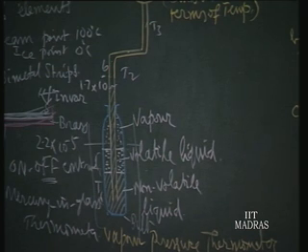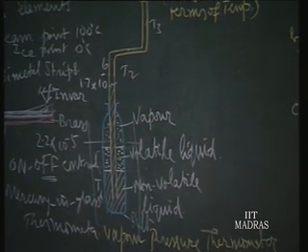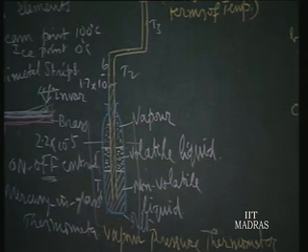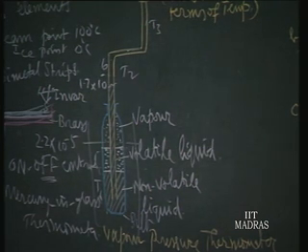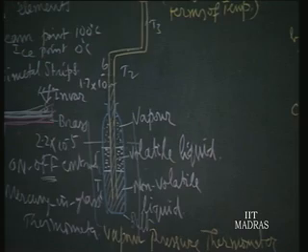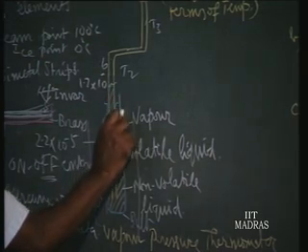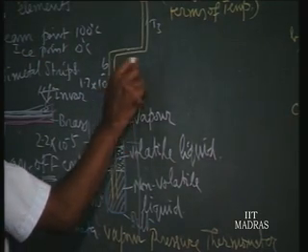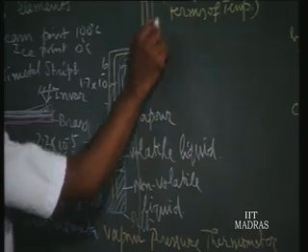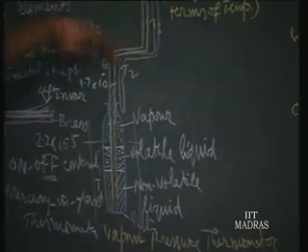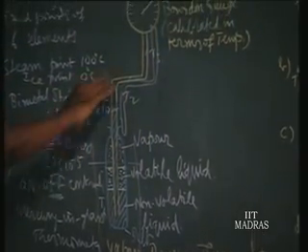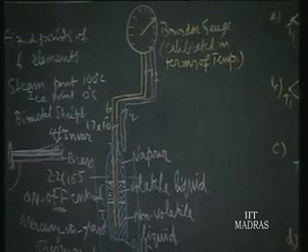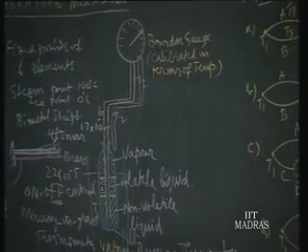Hence we find the vapor pressure thermometer is more accurate than the liquid pressure thermometer. Hence this vapor thermometer is often used. If you are using a liquid pressure thermometer, then for compensation we should take another tubing, and this much expansion is given in the opposite direction, so that any error is compensated. So it is a little elaborate in construction and more costly.